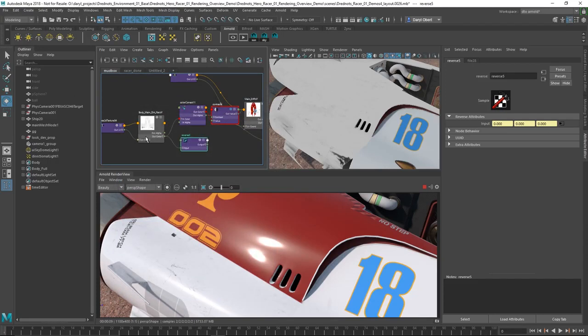The next thing that we want to do is modify the value range that it's using. We want to keep that full range of colors, but we want to limit them from being the old range that used to be black to white, 0 to 1, down to something that's going to be good for that roughness value, which is going to be something like 0.05 or 0.01 to 0.4.